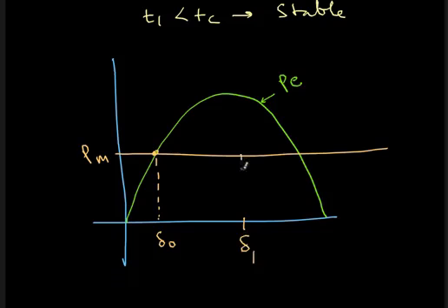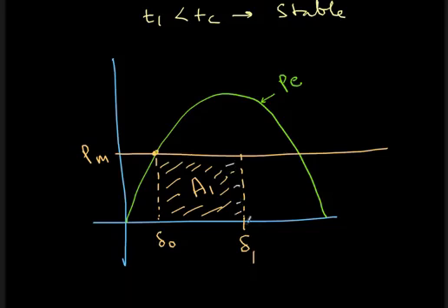So then this much energy is actually stored in the rotating mass, which results in an increase of the acceleration of the machine. Now, how to get back that energy? So at this point, delta 1, I had cleared the fault. So therefore, after clearing the fault,